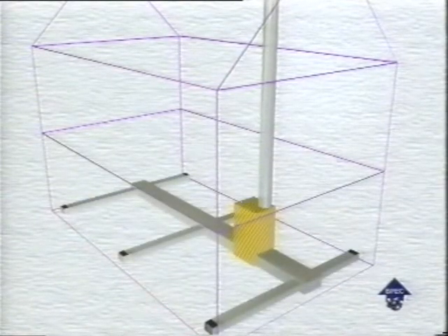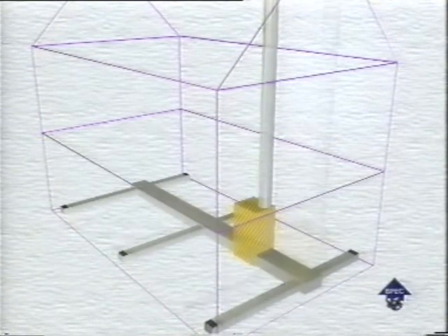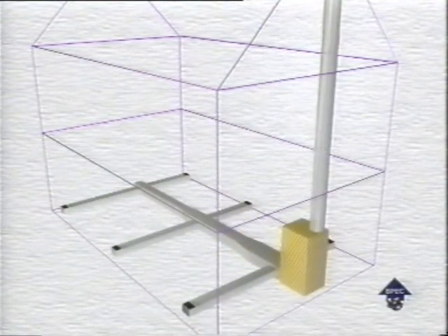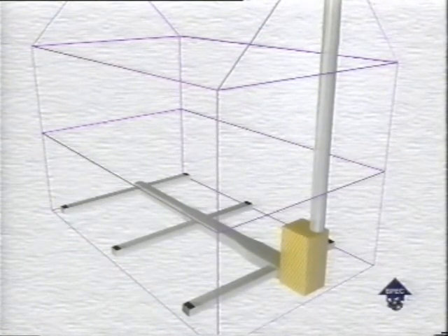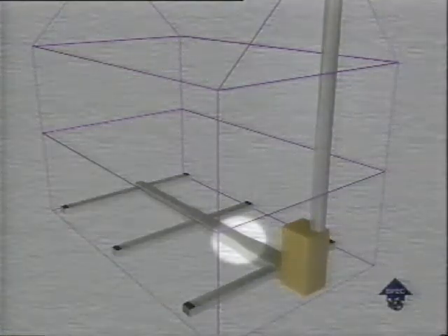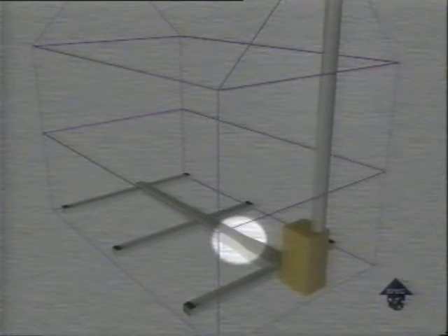With an extended plenum, the main duct is the same size throughout, and different sized ducts branch off it for the various rooms. When the warm air unit's at one end of the house, the arrangement is usually a stepped duct. As branches are taken off and therefore less air passes through the main duct, its cross-sectional area is reduced.